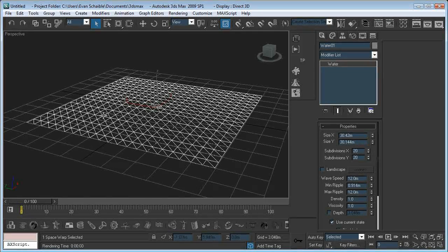Otherwise, we're just going to get rigid edges and you'll be able to see triangles in there, and a lot of artifacting and things like that, which we obviously want to avoid. So what we're going to do is, for 30 by 30, I think probably a good subdivision level would be about maybe 45, 50, 55, somewhere in there. So in this case, let's just go with the highest level that we think would be appropriate.